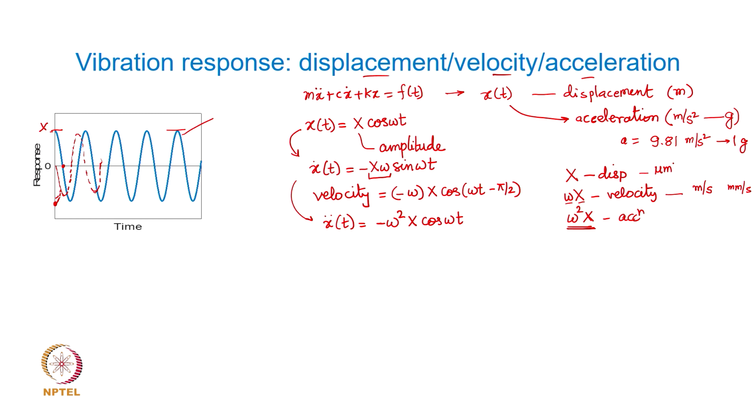Okay. So, just to give you an example, our power plant rotors, the steam turbine rotors, typically will not have vibratory motion exceeding maybe about 50 microns or so. If it goes beyond 150 microns, the turbine is supposed to trip, and it is designed to trip when the values of the lateral vibration amplitude go beyond 100 microns, depending upon the capacity and the unit.